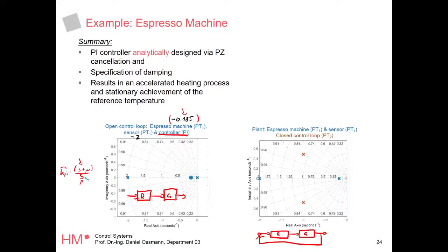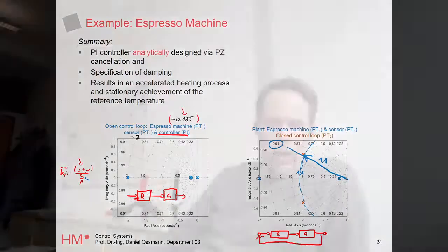And if you look closely, it has a damping of exactly 0.9. 0.91 is this line here, and it's slightly above. And the eigenfrequency, these are these circles here. You should see it's roughly 1.1 here. There's this 1.1 circle going here. So the eigenfrequency of this guy is 1.1. Okay. So this would be the pole-zero interpretation of our system.